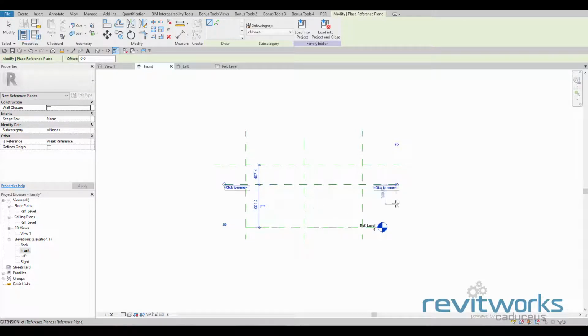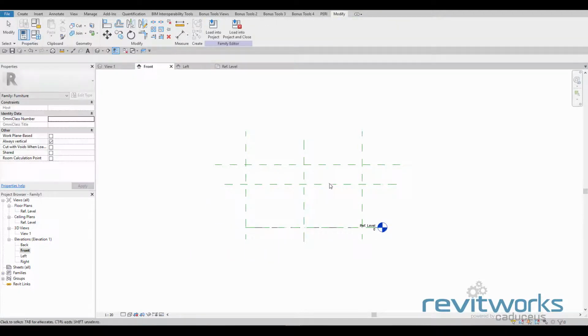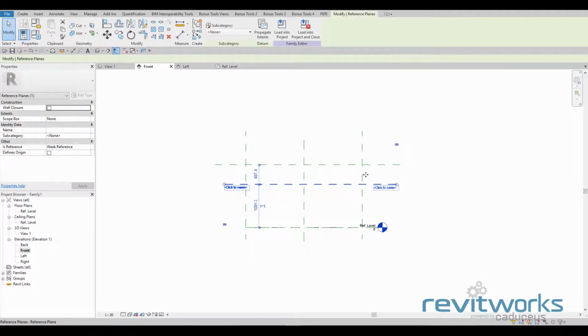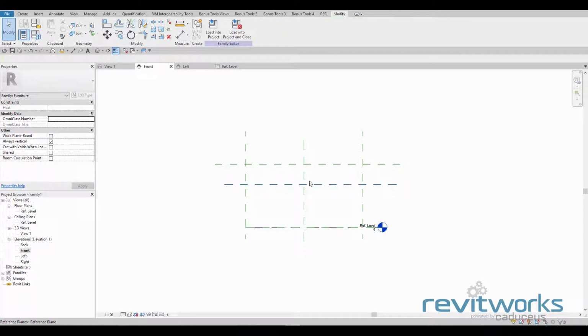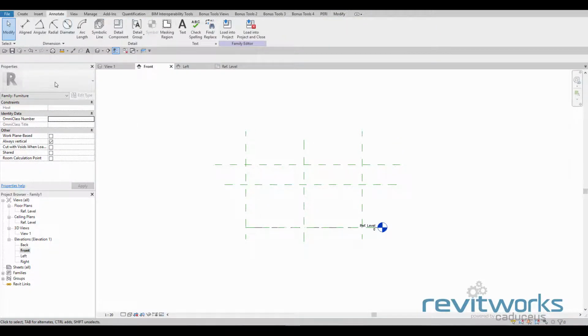In fact, whenever you're modeling or creating families in Revit, you're generally trying to make them the wrong size and then push them back to the correct size at the end through their parameters. That's another great test. But also, if that tabletop was really thin, then that reference plane had to be sort of up there. That's just harder to work on when they're close. You may as well make life easier on yourself. Put it back there.